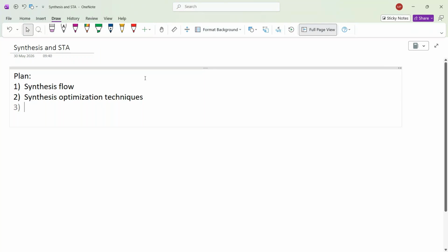As everyone knows, in physical design, whether it is synthesis or PNR, PPA is really important. So we work towards PPA to achieve better power, better performance, and better area. Here, how to achieve power reduction techniques. These are really important as far as physical design synthesis is concerned.